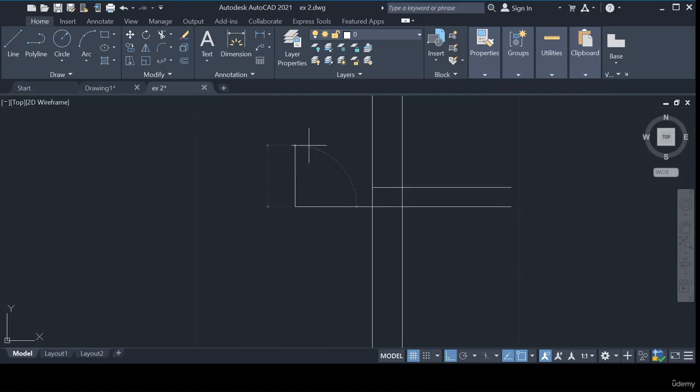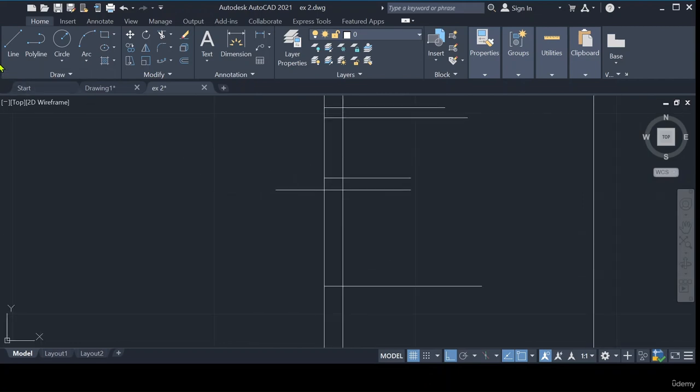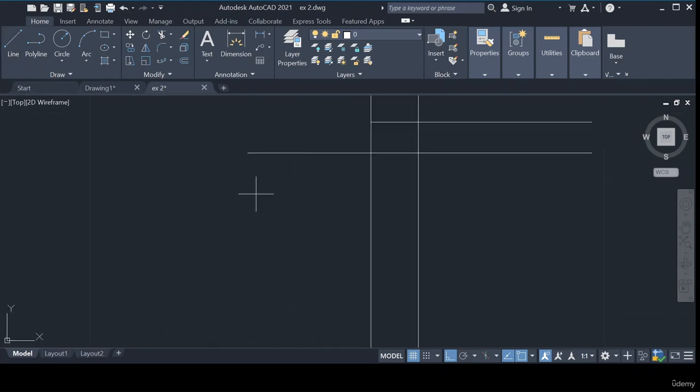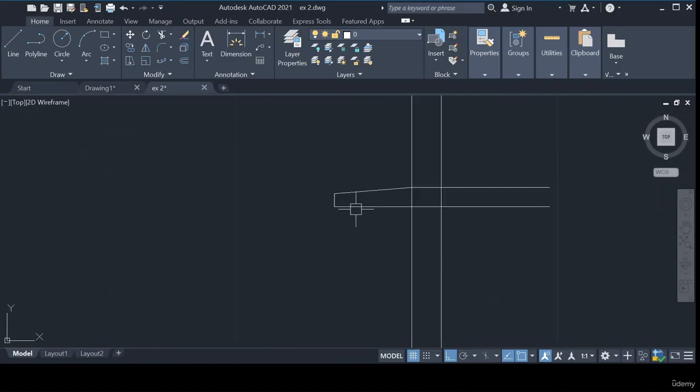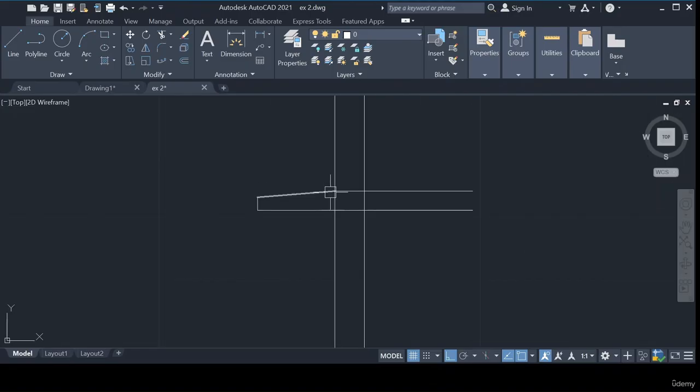What is the thickness? So here I just do one thing. I just take a thickness at the projected end. The thickness of the chhajja is 0.1, and at the lintel level the thickness is 0.15. I am providing a slight slope here, so whatever rainwater comes, it will easily drain off.